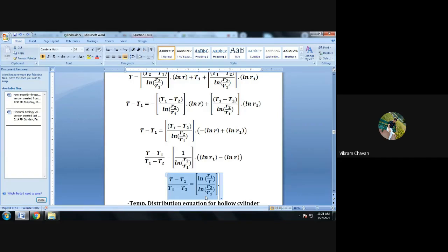Is everyone getting it? Did you understand? This particular equation is called the temperature distribution equation for a hollow cylinder. So what is the significance of this equation? If you know the internal surface temperature and external surface temperature of a cylinder, and you know the internal radius and external radius, then if you want to determine the intermediate temperature...